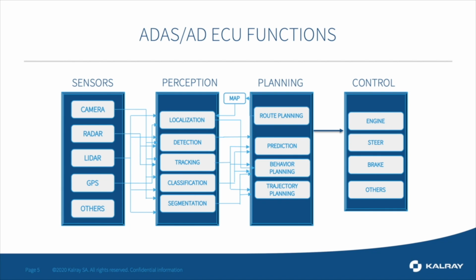Obviously, everybody understands the camera is very useful for identifying signs on the road, while LiDAR helps in understanding the environment topology, and radar can be used in other environments such as night or limited visibility as well. The combination of these sensors makes the system more reliable because more data can be fused. And sensor fusion is one of the key entry points for the perception module.